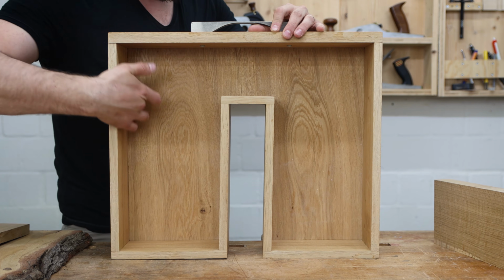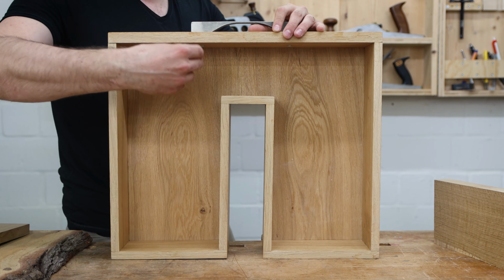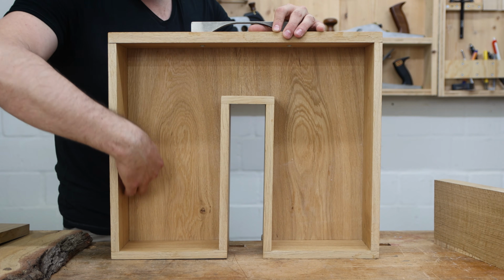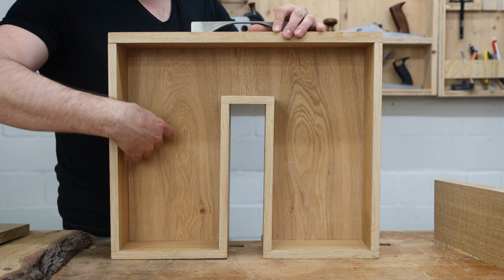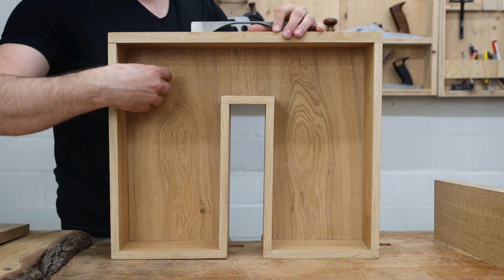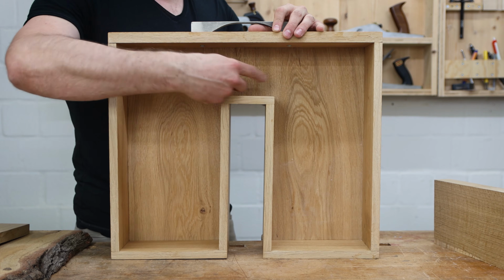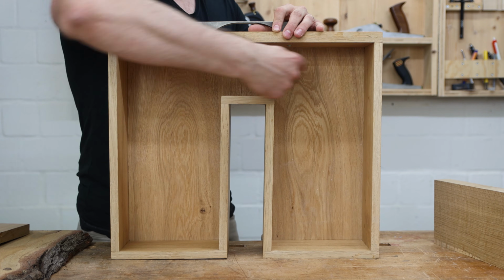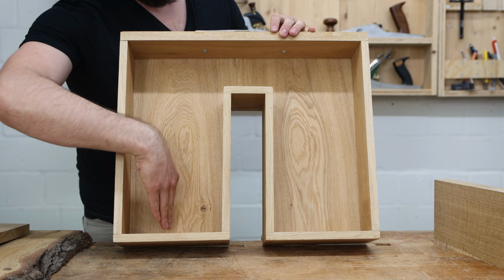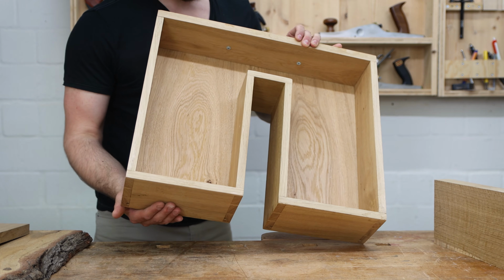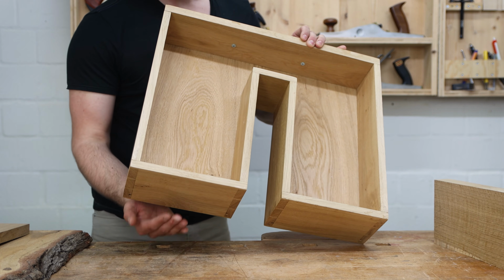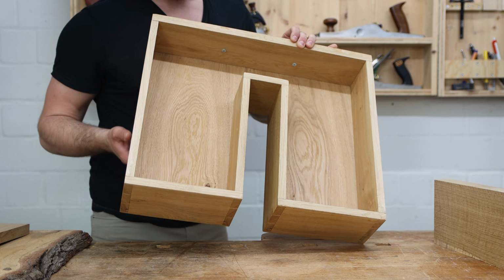Now I have a small gap here. So I should have made the bottom a little bit wider to leave it in that groove here, and maybe make that groove also a little bit deeper. However, usually you do make your bottom the other way around, with the grain direction running this way, so it can expand to the back. Usually you make it so it sticks out at the back, and it can expand and contract here freely and you don't have to worry about it.